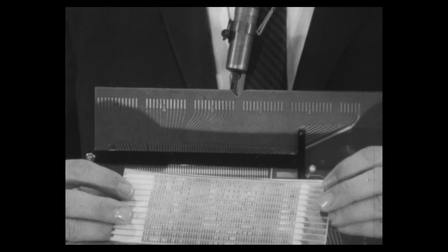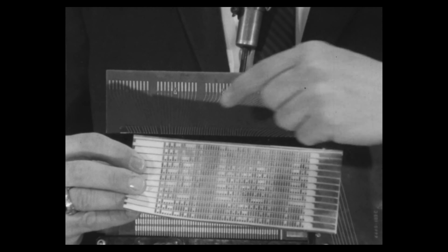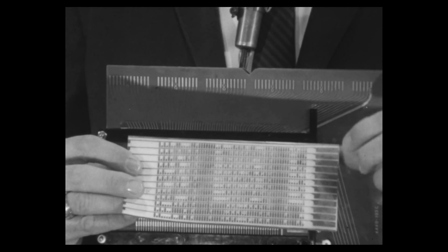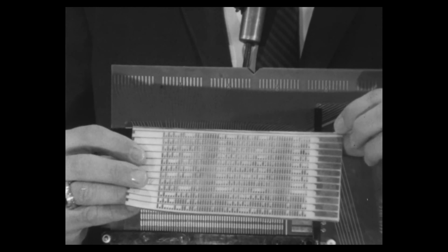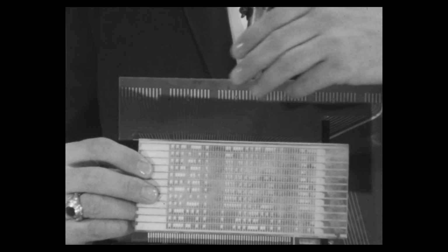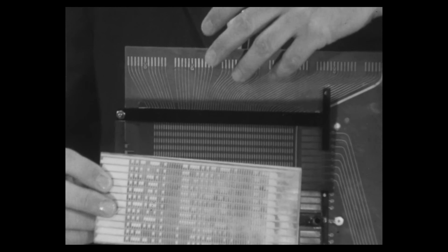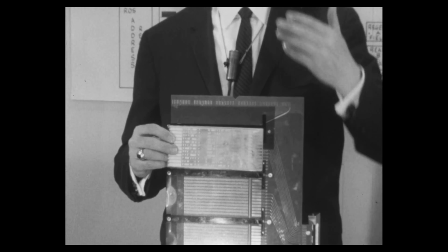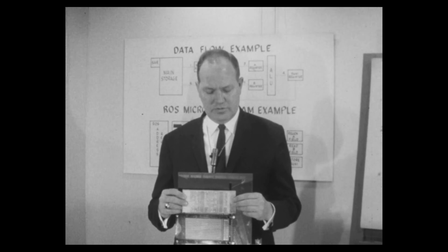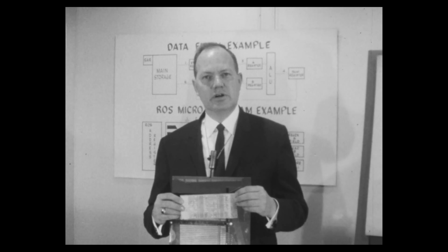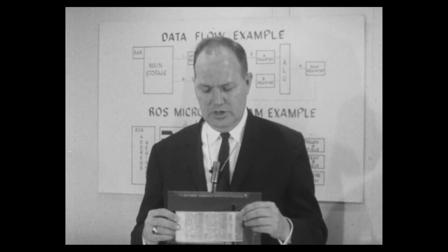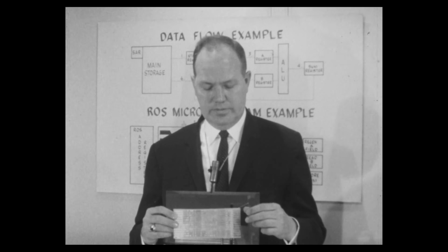In the case of the Model 30, the engineer determines a bit pattern for each microinstruction word, and these bit patterns are sensed and sent out through this sense board into the machine such that they will cause various circuits to gate, open or close, to allow the transition of data or the movement of data through the machine. Read-only storage also takes care of the problem of getting timed impulses through the proper circuits at the proper time, under control of the bit pattern.